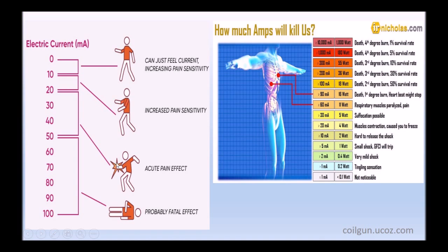It means that a human cannot disconnect himself from the current-containing part at such current levels. Then in a range of 50 milliamperes to 100 milliamperes, fibrillation takes place. It's chaotic heart-muscle contraction, and at more than 100 milliamperes, death takes place. All this, of course, depends on the place of application of our electrodes and the distance which current runs through our body. The worst case is considered to be from the left shoulder to the right leg. It means a very long distance, and along this distance current runs through the heart. So that is the worst case.